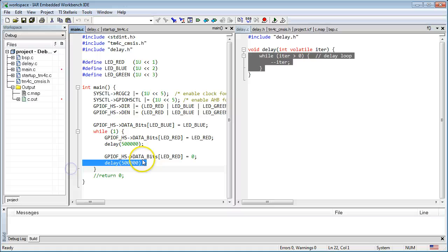This will become much clearer in a minute, but the point is to test this, still with the old polling approach, before venturing into something new, like using interrupts. So instead of relying on the sequence LED on, delay, LED off, delay, you can observe that before each delay the state of the LED needs to toggle. If the LED was off, it needs to go on, and vice versa.